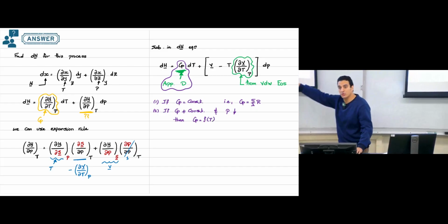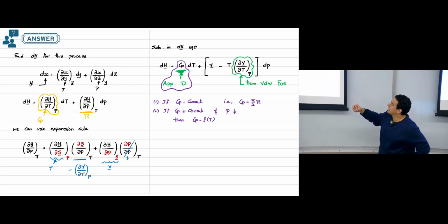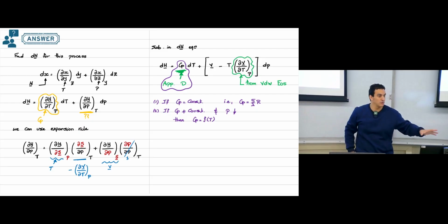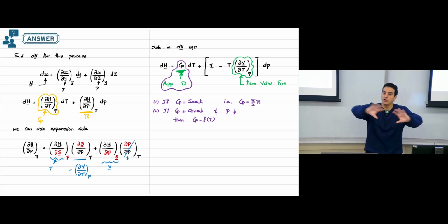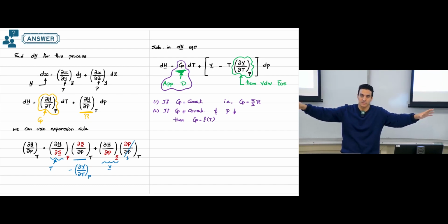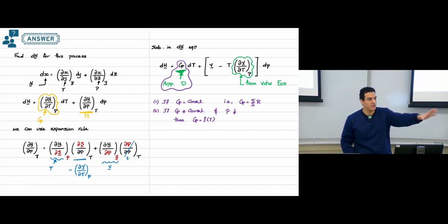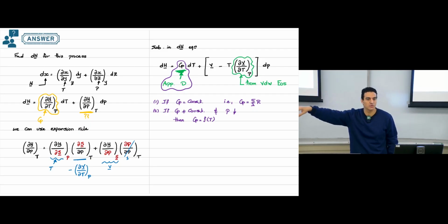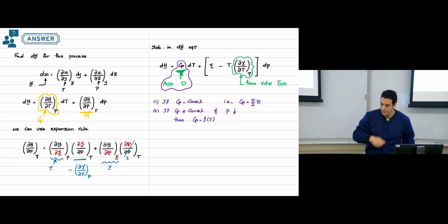Then we can go to appendix D, pull the equation of Cp, put it here, and make the integration. We solved this in chapter 3. The long equation of Cp from appendix D gives A (T2 minus T1) plus B over 2 (T2 square minus T1 square) plus C over 3 (T2 cube minus T1 cube), and so on.